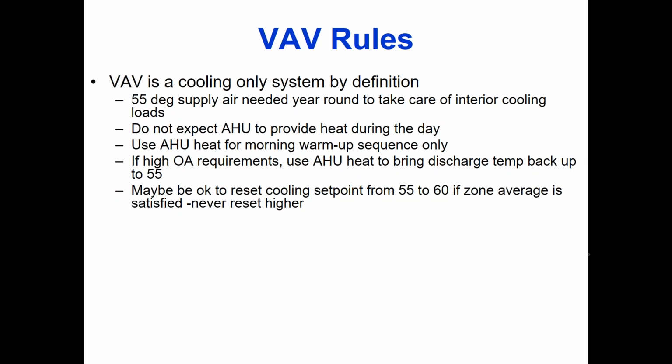Let's take that back. If I didn't put one VAV air handler on the whole floor, like I showed you in my other drawing, my floor plan drawing, and instead I put a small VAV unit on the east, another one on the west, and one on the south, and one in the core, if I divided it up like that, put 4 small VAV air handlers in, then I could get away with it. I could actually do it. Because then I wouldn't have zones that wanted opposite things at the same time. I wouldn't want somebody that wanted heat while somebody else wanted cooling. So I can get away with it if I did it that way. But if I had one floor laid out, it's not going to work very well. How am I going to give you 100-some degree discharge air temperature for the perimeter zones when the interior zones want 55-degree cooling?